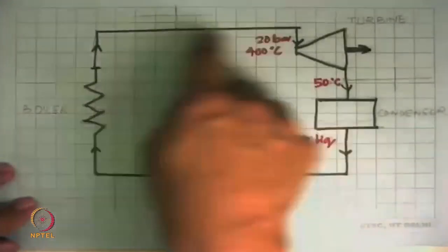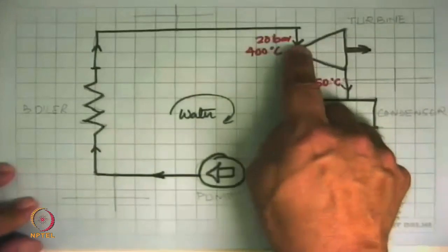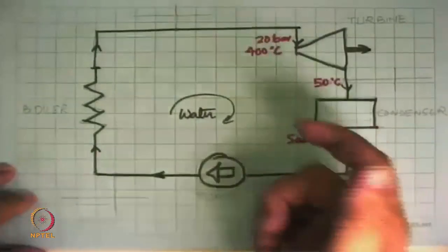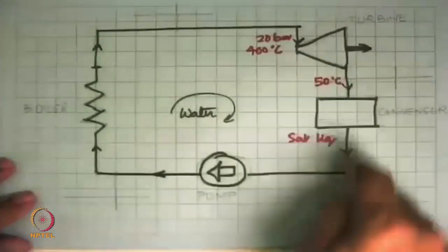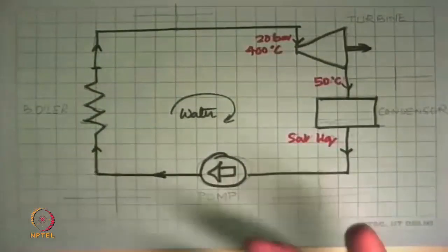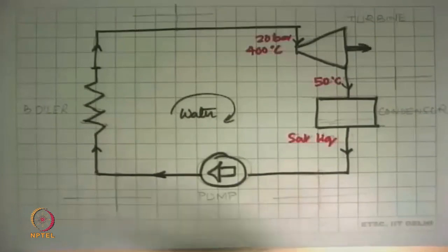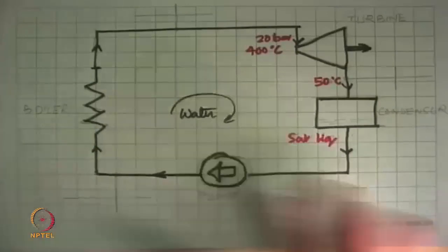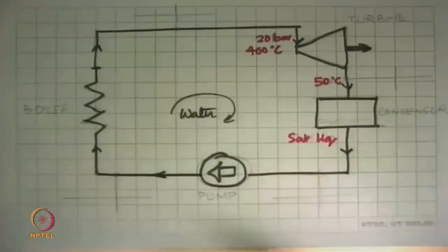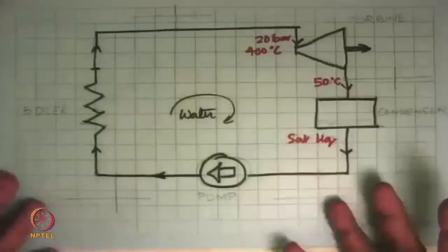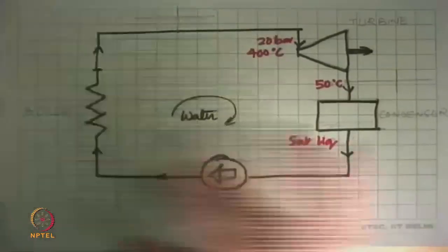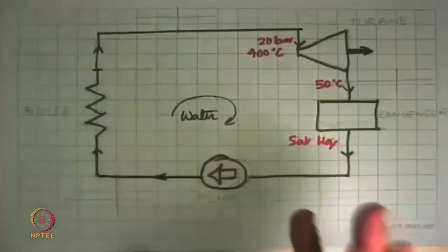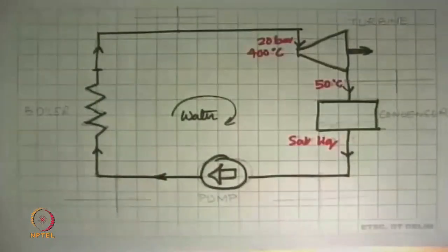And these states tell us what is the pipe diameter and the material and the type of pipe that you are going to put for these types of conditions. So the cycle as such, what we are going to do now, is the basic first step that one does in the design of any power plant or any cogeneration system or any combined cycle power plant or any other place where such a flow system is done. It could be a refinery, a paper mill, anything. This is the first diagram that is made, and you put mass balance and energy balance on this and work out what are the parameters that you are getting in this.